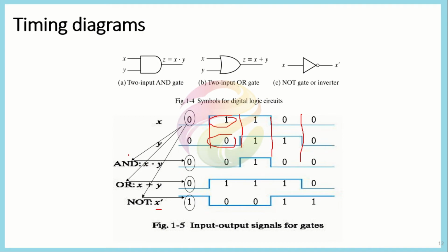So for the first step, what we do for a timing diagram is we generally divide it into different sections like this. First, we check when both of them are the same, then the next transition, and then the next transition. If you first convert this timing diagram into these columns, then it is very easy to represent anything, because then you only have to look at this. This is 0 here, so you will write 0 here. You will write 0 here, and you are taking the complement, so we will write 1 here.